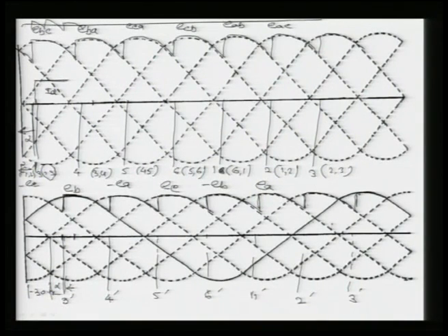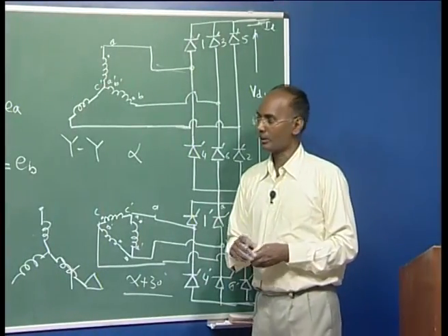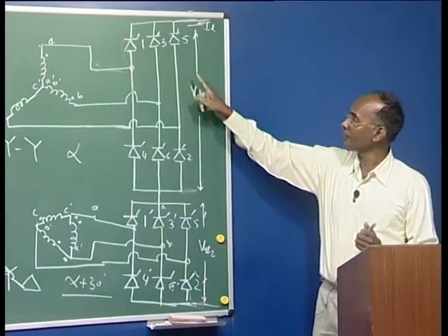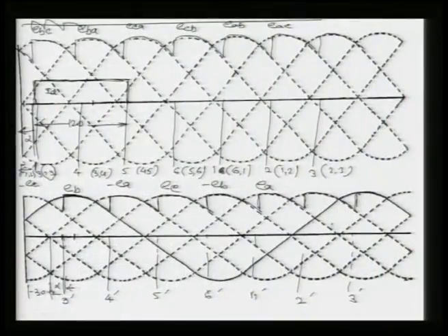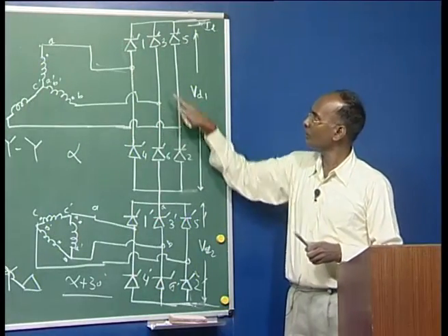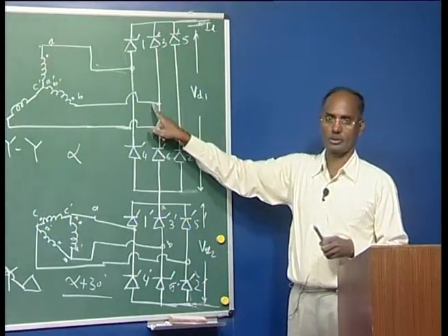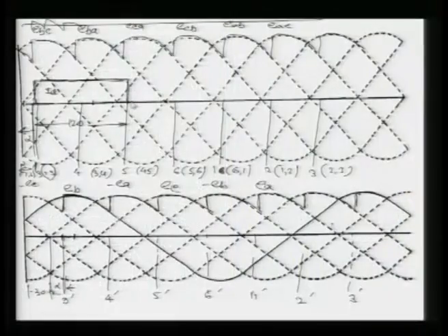It will go all along as long as 3 is there. It will go up to 120 degrees here, because the commutation between 3 and 5 is going to be over. So, this period is your 120 degrees. Now, the commutation is over, only 5 is taking. So, in the period when 4 and 5 conduct, this is going here and coming all the way here, both are off, and in that condition the current here will be 0. So, this will be 0 up to here.